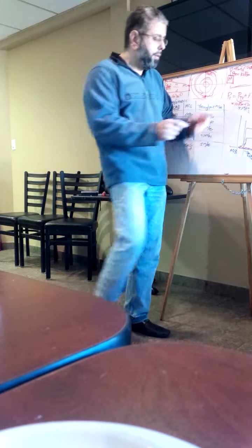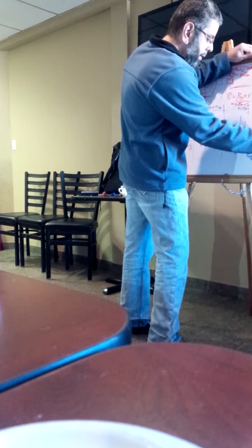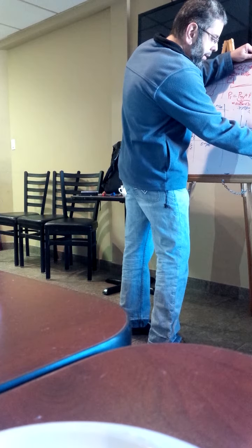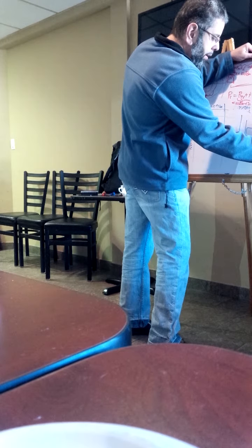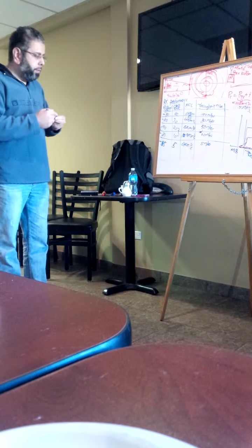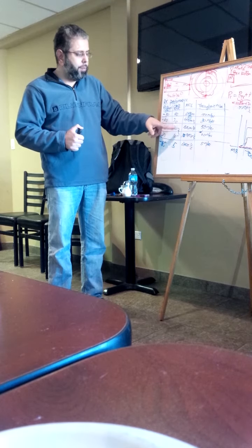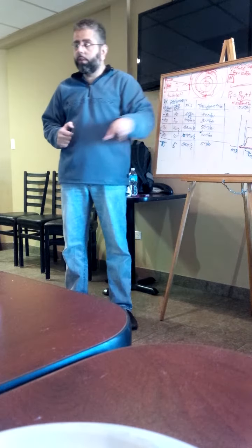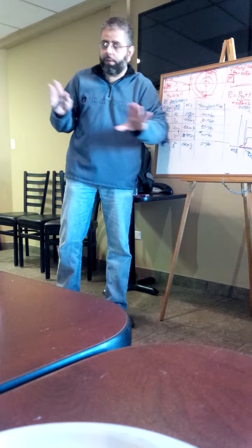So the center here is going to be minus 50 and the interference minus 70 dBm, for the sake of making it easy. Minus the minus 70. So now my new center is only 20 dB, right? So when you're at 20 dB, the thing starts to make sense that, hey, there's some interference here. If you were to do a spectrum analysis, you could find this. So how else would you find this? And how would you verify this?